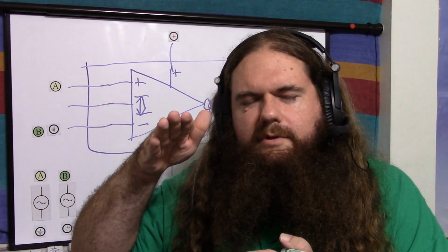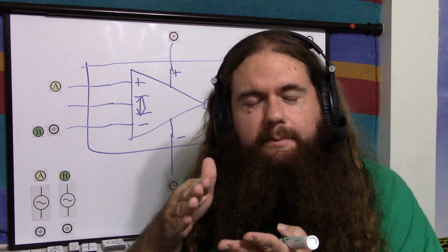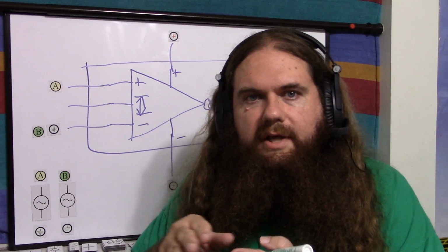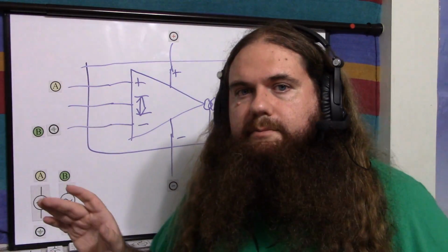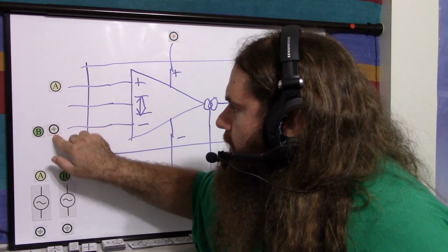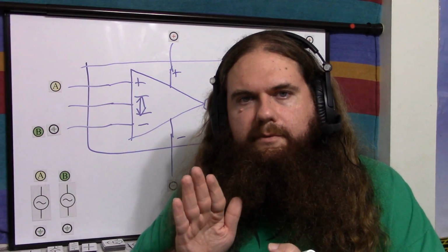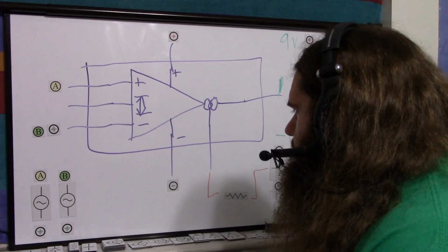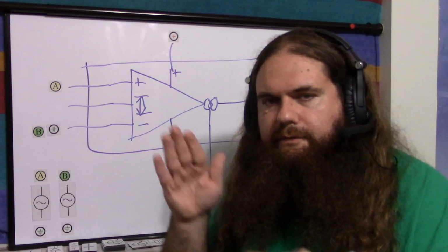So 0.5 volts, bring that down to 40 millivolts, 80 millivolts if you're brave, and you're using these diodes, but just a few millivolts, and then it'll be fewer millivolts if it gets quieter. So you set based on the maximum. So set a voltage divider that's going to bring your ground or B or whatever, so that the difference is never more than however many millivolts based on your input signal. And that's how you decide that resistor. So the linearizing diode just makes it behave better if you have a bigger difference in voltage.